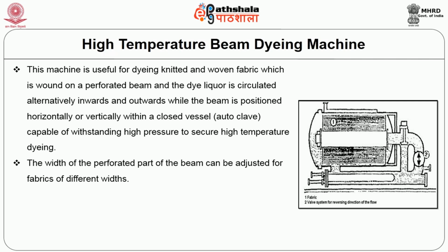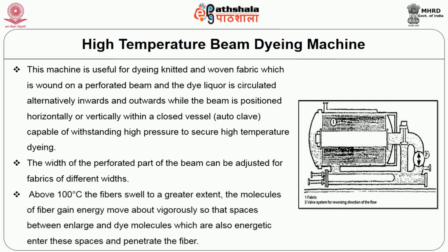The width of the perforated part of the beam can be adjusted for fabrics of different widths. Above 100 degrees centigrade, the fibers swell to a great extent. The molecules of the fiber gain energy and move about vigorously, so that spaces between them enlarge, and dye molecules, which are also energetic, enter these spaces and penetrate the fiber.